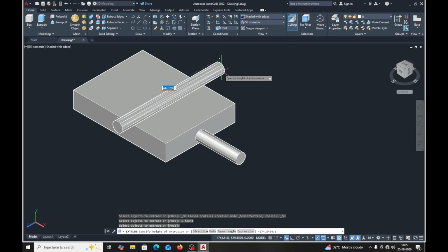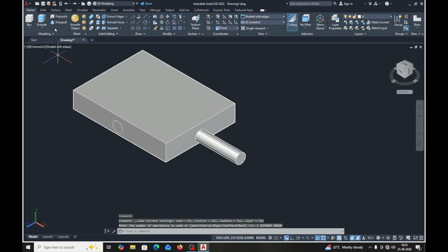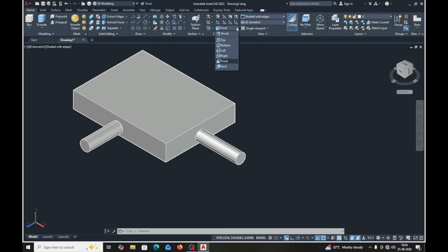And if you go inside, no, undo, extrude, select, enter. Extrusion takes place. You can give the dimension also. Suppose you want to work on this top face. You will have to change to world or top. Now, suppose I want to make an arbitrary sketch here.